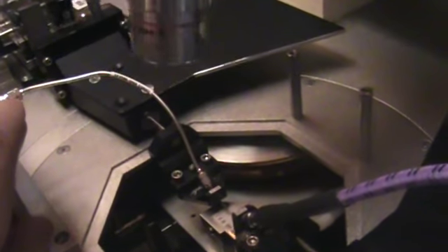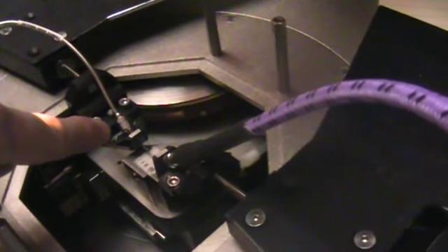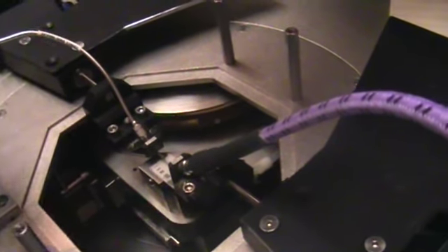Now on the port 1 side, the longer Gore cable extends into the source tuner. So we have a reference plane we can think of right on this side of the tuner. And then on the other side of the tuner, we're going through an Anritsu 2.4 millimeter barrel to a flexible piece of 2.4 millimeter coax. So we have about 5 or 6 inches of coax from the side of the tuner down to the input side probe. All of this will become a part of the characterization for the tuner.